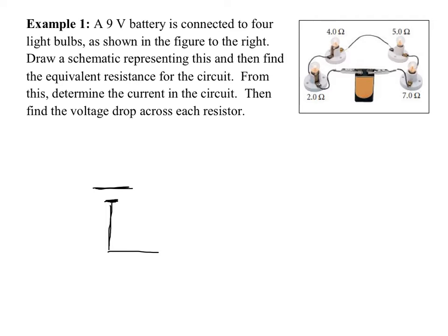Now, I don't know which of these terminals is positive or negative. For the sake of this, I'm going to put a positive there and a negative there. All right? I'm doing that in the diagram up there. I didn't know which terminal was positive or negative. In the diagram, though, I know that the smaller line is negative, the larger line is positive. Always, always, always. If you forget that again, think about a plus sign stacked on top of itself, which makes a longer line. So after the negative terminal, we follow the flow. What does it hit first?